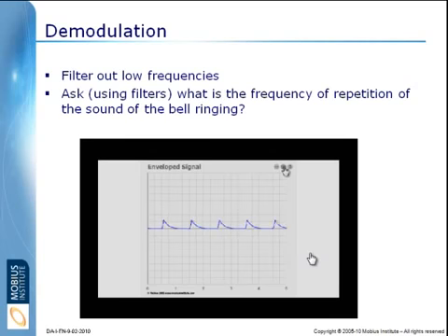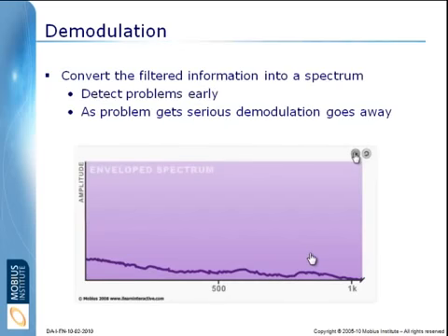And this technique is called demodulation. Again, the result of this is to find out the rate at which that dinging is happening, and that is our bearing tone frequency. It is a different way to get to the same information.